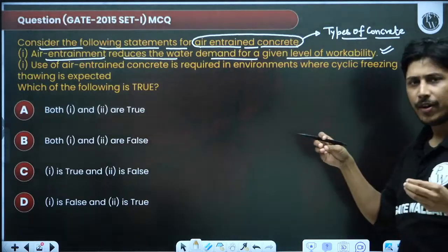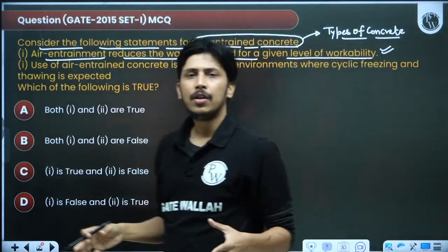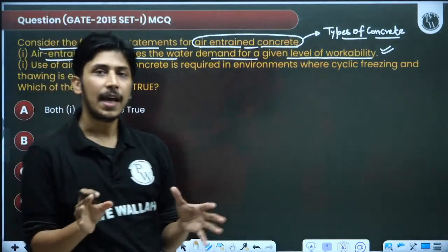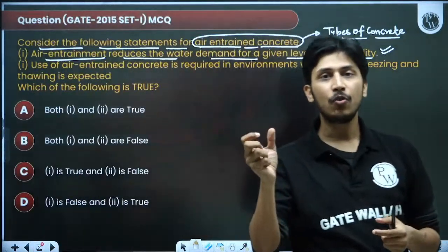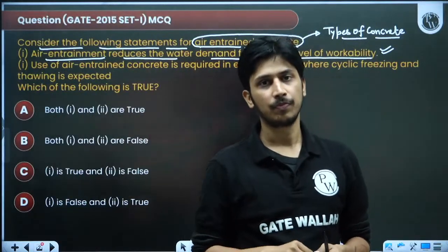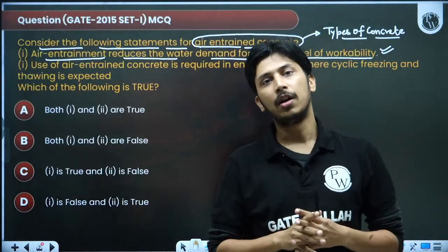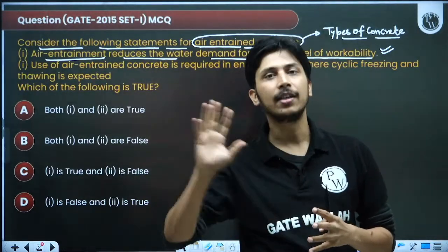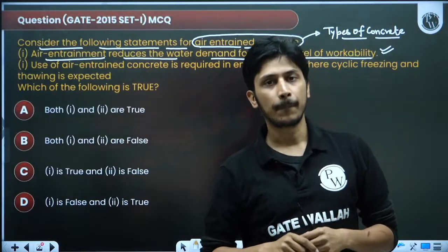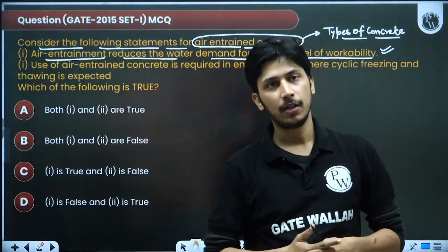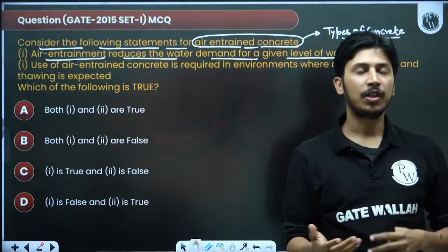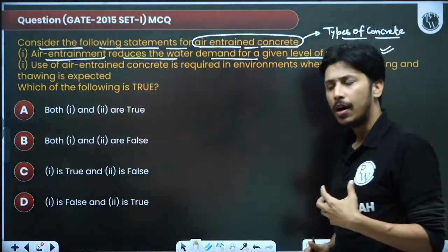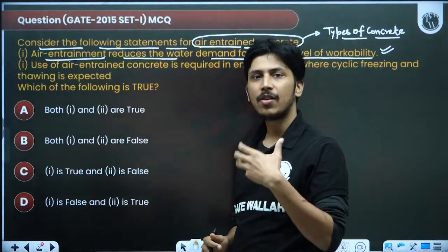Whenever you are entraining any fluid, whether it is air or water, like when a pipe is choked and air is pumped in with pressure, because fluid is a very good element to move anything, to slide anything, to push anything. So for movement, the fluid is very important. If you are entraining air, then you will require less water for workability. This is absolutely correct. So air also acts as a workable material. Air also makes the concrete workable.